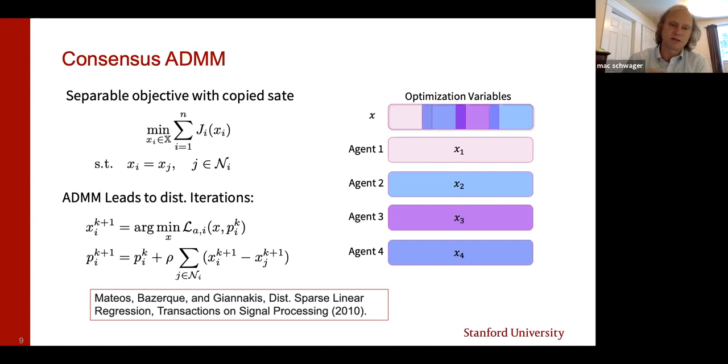So there's a primal step, which is kind of a small scale version of the original optimization problem that only requires data that's available to each individual robot i. And in particular, that robot is optimizing the augmented Lagrangian that's associated with this consensus ADMM. I'll show you details later, but just suffice it to say, it's its own individual instance of this kind of optimization problem. And it's performed entirely by robot i. It only requires information available to robot i.